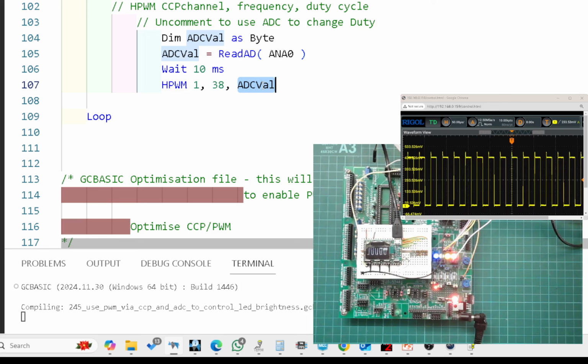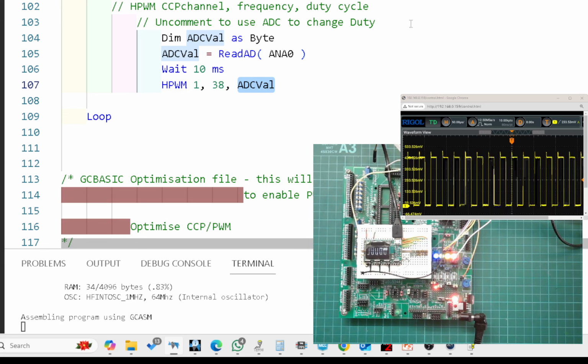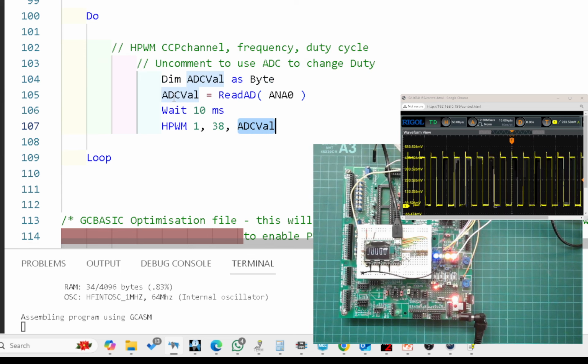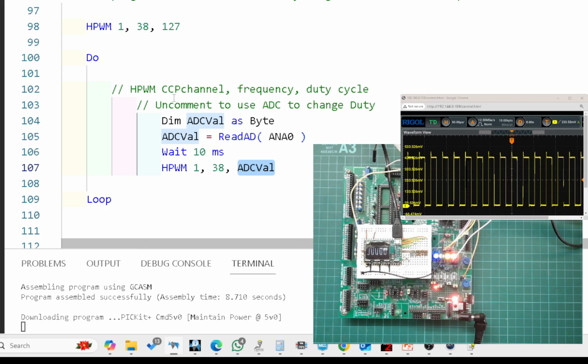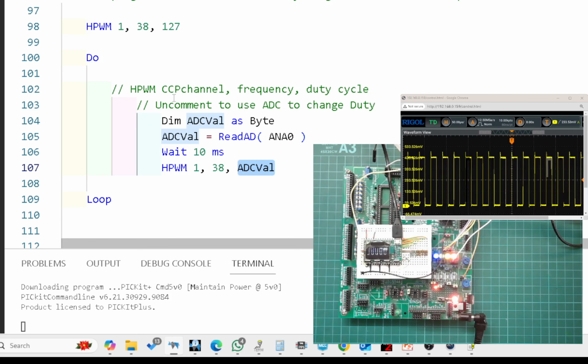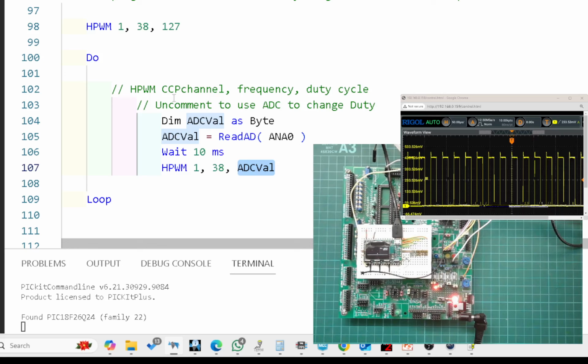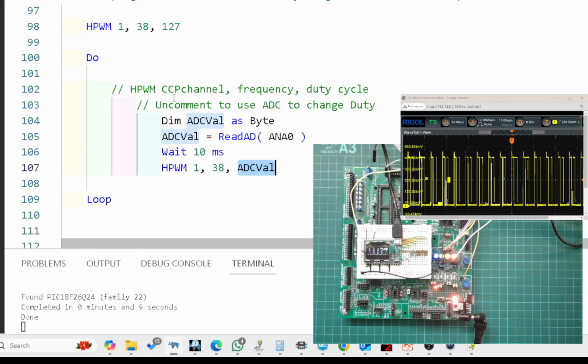And whilst I was talking, I programmed it by pressing function key F5, and we will see that in a moment, when my computer's made its mind up, to do its funky stuff. Now it's just assembling it using GCBASIC. And using this method, the constraints within the chip frequency, I've currently got it set to 64 megahertz, it will recalculate all the parameters for you. The same parameters we saw on that terminal, but they're all done dynamically. So it uses a lot of assembly to do this.